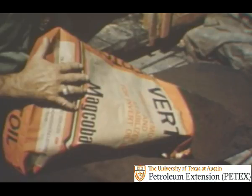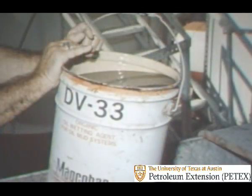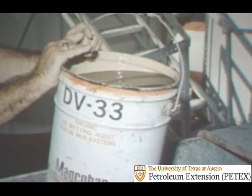A basic oil mud ingredient is mixed to emulsify the water in the oil. The material also contributes to the viscosity, gel strength, and filtration control properties of the mud. Other supplemental emulsifiers and oil wetting agents are added to support the basic ingredients and to assure all solids stay oil wet during the drilling operation. These components are thoroughly mixed into the oil.